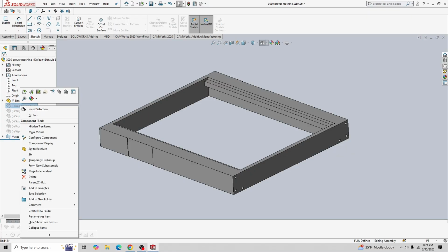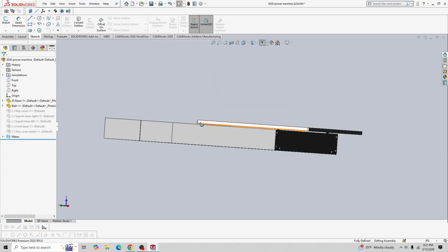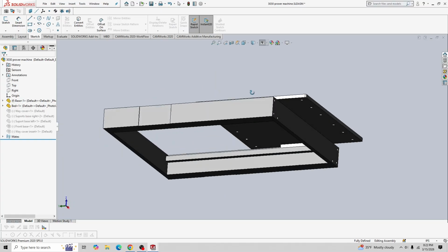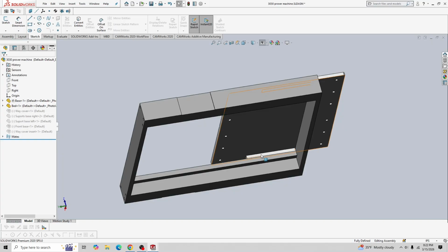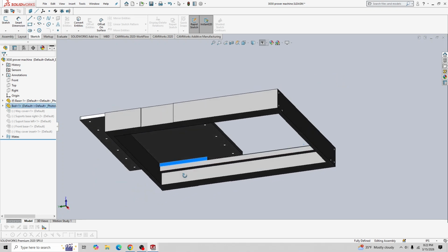And so next I created the bed of the machine. What I've done with the bed of the machine is underneath I created a few blocks, and these are just simulating the rails, the little carriages that go on the rails. This would be your linear rail here, but we kept it light and simple. And so what this does is, I put constraints on it, so it can't go any further than here.